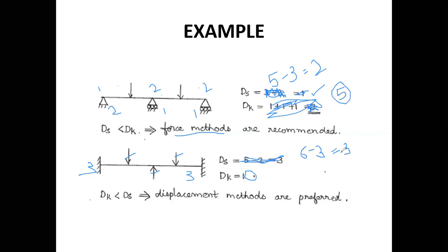So in this case also, the degree of static indeterminacy we have seen is greater than the degree of kinematic indeterminacy. Hence, we will prefer the displacement method for the analysis. So this is how we will be choosing the appropriate method for the analysis of different indeterminate beams.